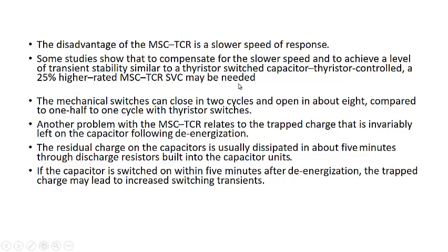That means when we use a mechanically switched capacitor, we have to use a 25% higher rated SVC of this type, which uses the MSC. In that case, we might have a similar level of transient stability, because we are finally discussing voltage control, and voltage control has a direct impact on transient stability, because transient stability also depends upon the voltage of the system. During the fault the voltage goes very low, and when we increase the voltage, the transient stability will increase, because the area under the P-delta curve will increase.